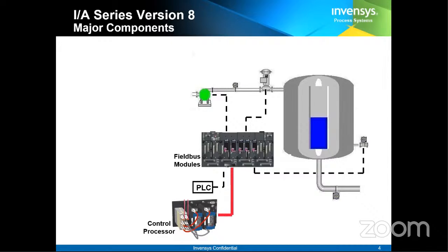So here, the controller output or the control loop output will be very oscillatory. It means if we track the complete waveform on an oscilloscope, you will find it's a kind of sine wave. But that is not desirable for me. So there, what I want, I will add integral.